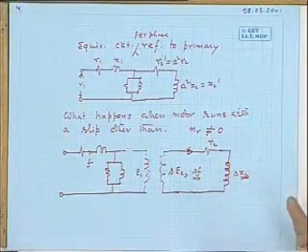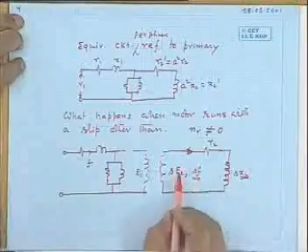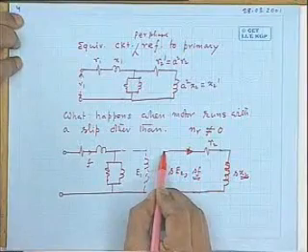And because of that interesting fact, no matter what is the rotor speed, the stator really does not know whether the machine is running or stopped, or running with some speed. It always will see that the secondary winding has produced a rotating magnetic field which is rotating with ns speed. And it will say that I can always counter this by drawing 50 Hertz current, because it can produce ns speed rotating magnetic field. That is the idea.